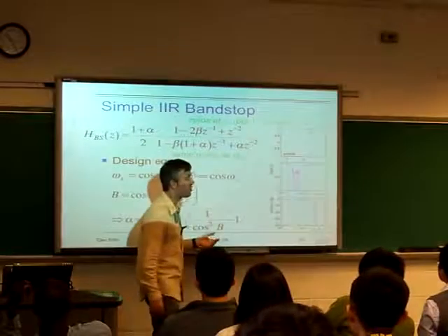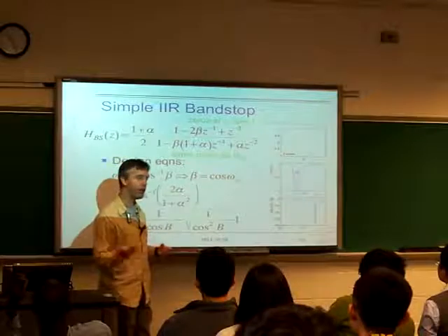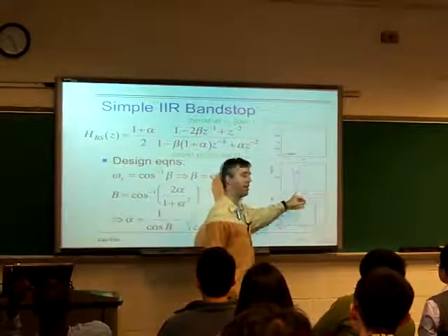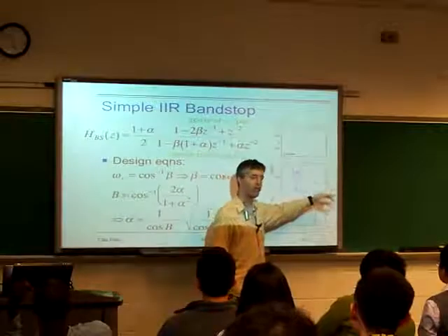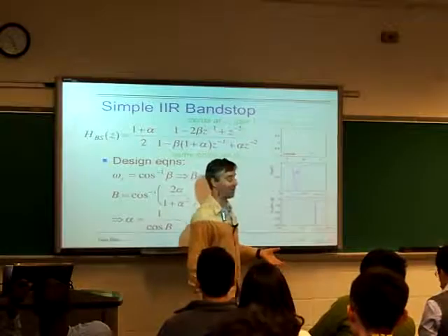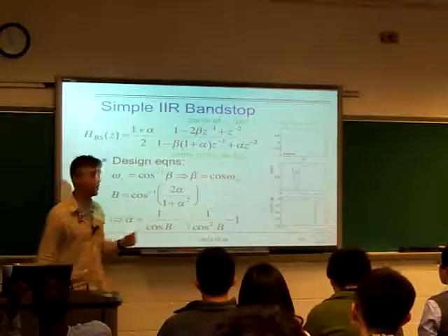I had this situation where we had hum on a recording. We made a recording, but there was some mains hum, which was at 60 hertz and then 120 hertz and 180 hertz. Put together a bunch of these notch filters. It's amazing how much you can do with something like that. It goes from being almost unintelligible to something that's quite usable.